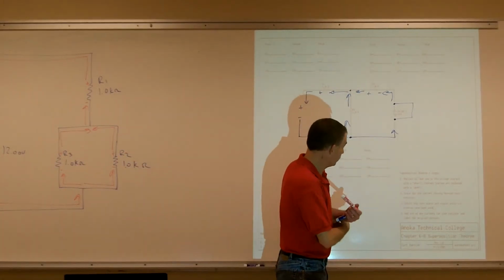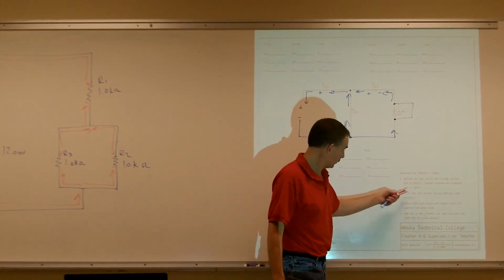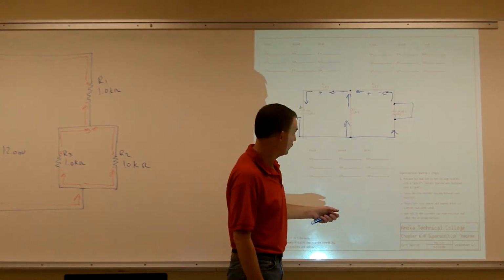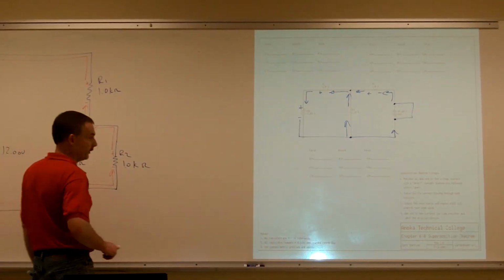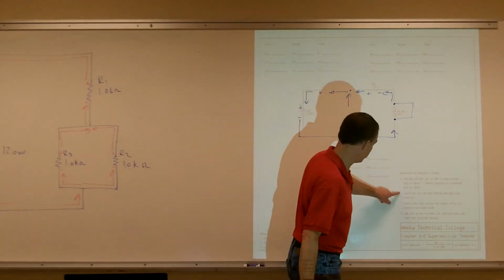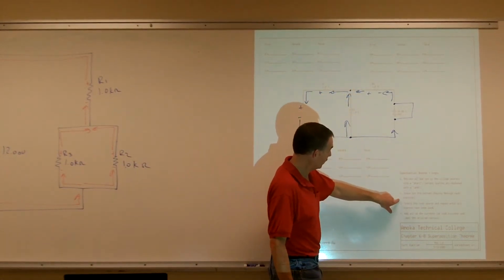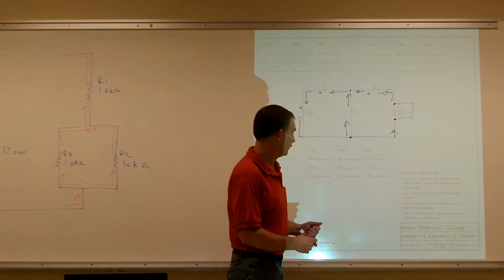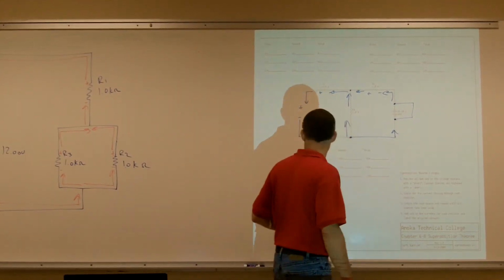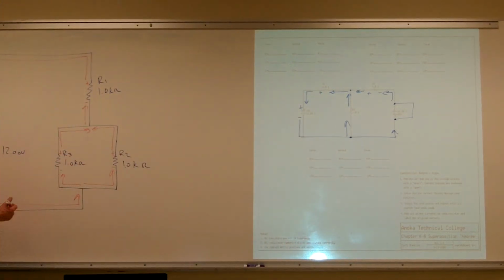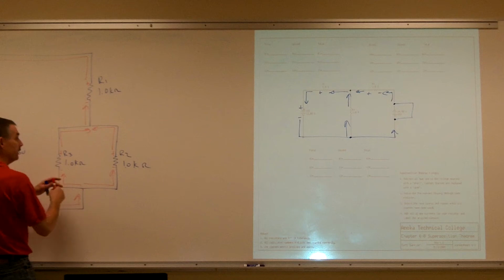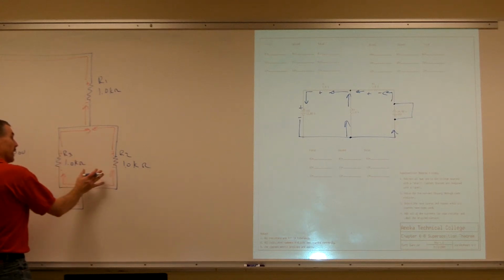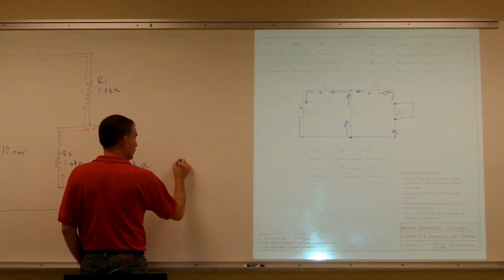All right. So then it says solve for the current that's flowing through each resistor. Okay, so we already did that. Now we need to calculate how much current is flowing through each resistor. We already determined the direction of the current. So again, we have to reduce it down to at least this series circuit. We're going to do some shortcuts here so we save ourselves some time. So I can combine R2 and R3 together, right? So then my equivalent circuit's going to look like